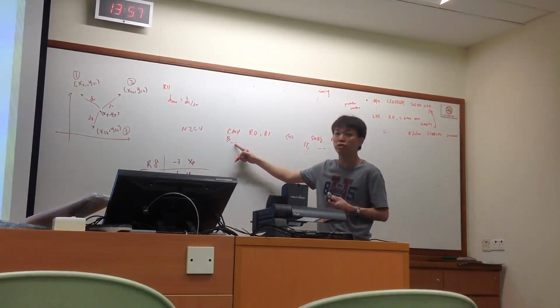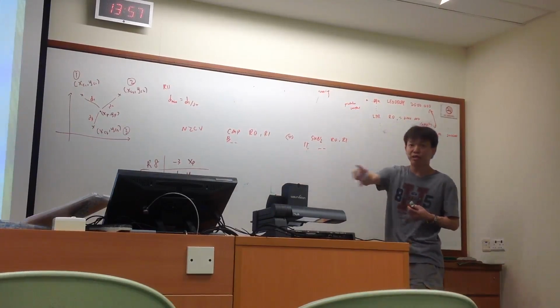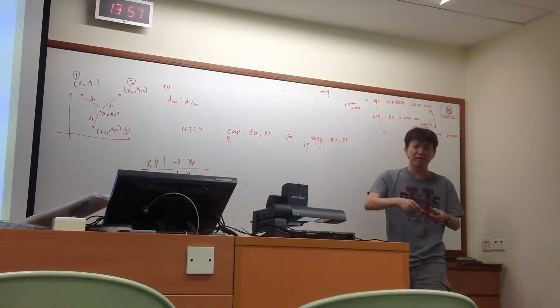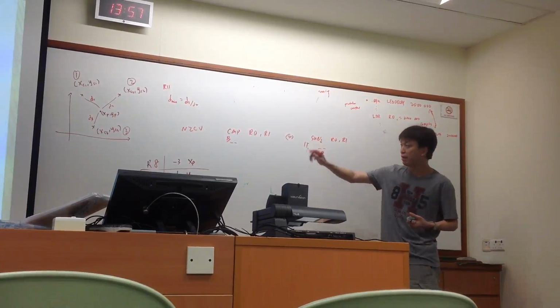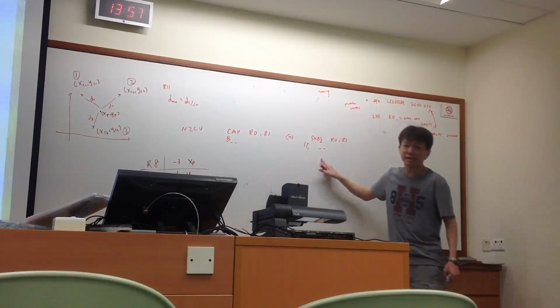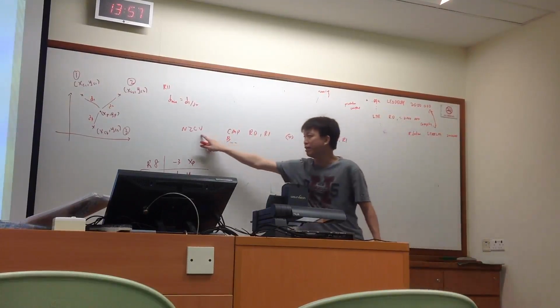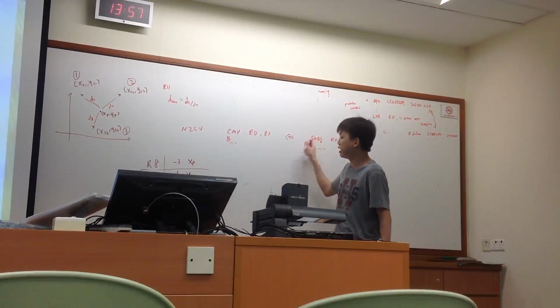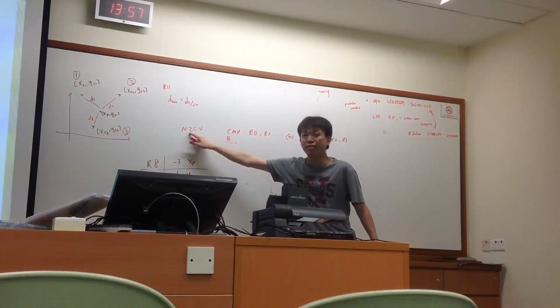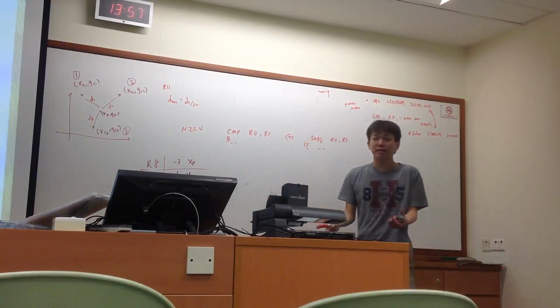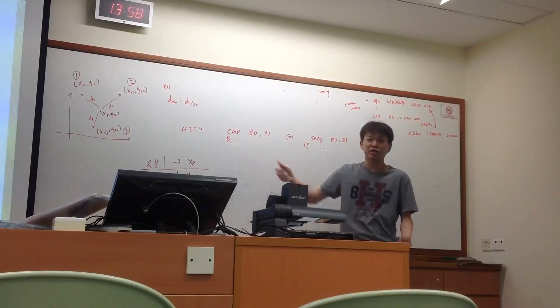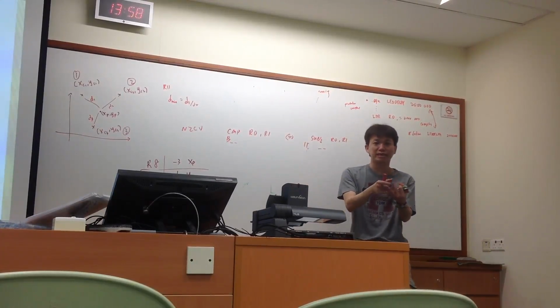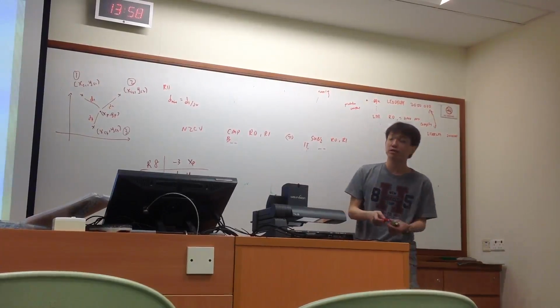That's all. So that's why you always need either something with the S suffix or use a compare before you do the branch or before you do the IT. You can check the notes or whatever tutorial or the example before the branch or IT. They always try to update, use the compare or subtract S to update the NZCV flag. You must update, otherwise the branch cannot check whether it's greater, lesser, or negative, or positive, or whatever.